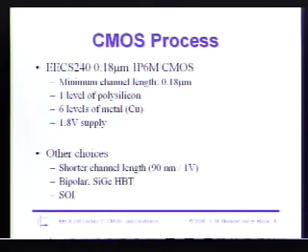And the way he did that was on the MOSIS website, they have postings for process variations of threshold voltage and mobility and other key parameters in a transistor, and by using that variation, he's put together a model that has corners, basically. And by corners, I mean you can simulate your devices at different process corners. We'll talk about this a little more next lecture. A slow corner, a fast corner, a typical corner. You can change the temperature, and hopefully everything works out well.